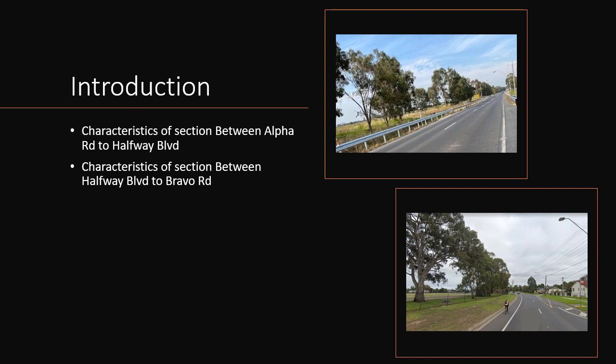the Alpha Road and Halfway Boulevard section is on low-lying area right next to a wetland reserve with very poor subgrade soil. It has very limited access to rural private properties and wetland reserve management requirements. The section will have rural characteristics with steel soldier verges, soil drain, and